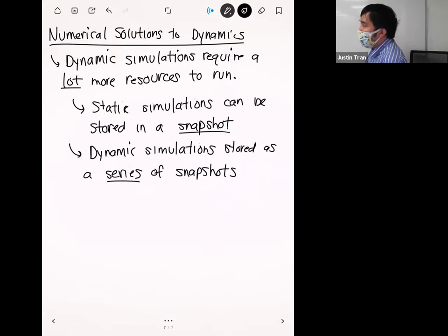30 times per second is actually not that fine. And so a lot of times you're going to be working with a time step size that's a lot smaller. You can basically think of it as solving finite element problems over and over and over and over. And so the cost for dynamic simulations can really get up there, especially if you're not careful with how you set the parameters. Okay. But that's okay. Probably what you'll see on Wednesday is that you're going to be spending some time waiting for your results to finish. And so don't panic. You didn't do anything wrong. That's just the nature of dynamic simulations, that they just take a lot longer. Okay.